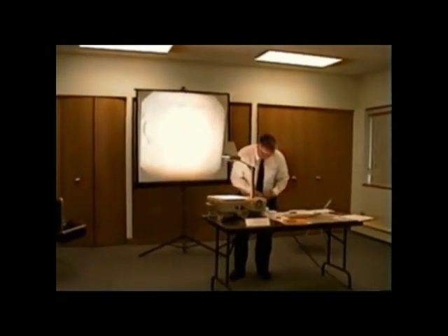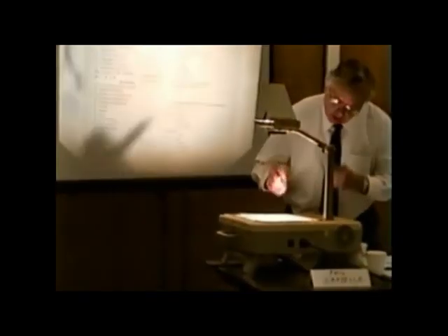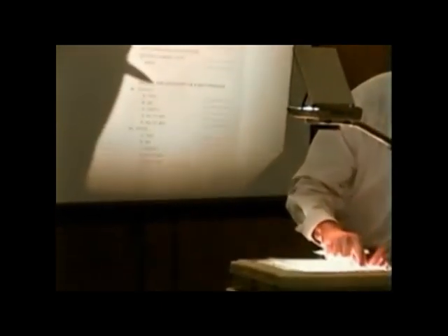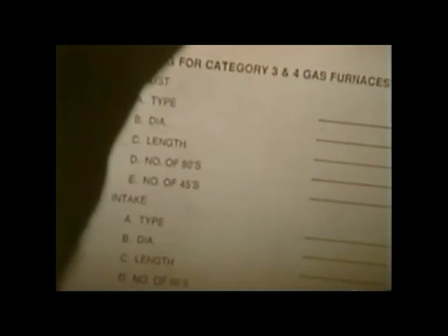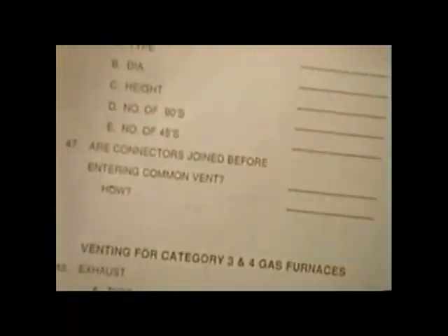All right. So, let's say now, all right, Jeff, we'll let you: line pressure minimum 5 inches and regulated 3.5 plus or minus 0.2, and if you checked it and it was good, what would be a good supply gas pressure? 6. 6 inches, and now even if he wanted to use a decimal, he could, but he's saying 6. Manifold gas pressure? 3.4. Perfect, I love it. 3.4, okay?